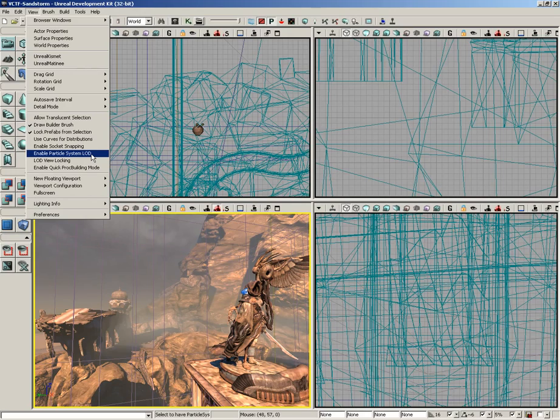However, by default, those sparks would be calculating unless there was a level of detail, an LOD, in place to take them away as the player moves further back. Switching on Enable Particle System LOD allows you to visualize those levels of detail right here inside your viewports. So if you need to edit them, if you decide we need to make that fire a little simpler if we're far away, or even make it a little more complex because now it's too simple, you can see that right here inside your viewport. You can also lock LODs in your view so that if you're far away, you can have the lower level LOD in place and then get closer and see what that low LOD looks like as you get close to it.